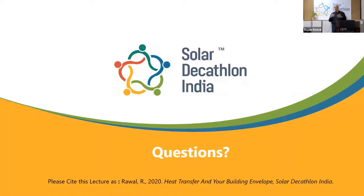You are solving the problem of solar gains by putting a creeper, but then you must have some other strategy to gain more daylight. Either have a creeper on the south side, or on the east and west side, but don't put it on the north side. Anyway, on the north side it will not grow, because it will not get enough solar radiation. And get daylight from the north side, or get daylight from the roof. There are multiple ways by which you can use creepers and still get daylight.